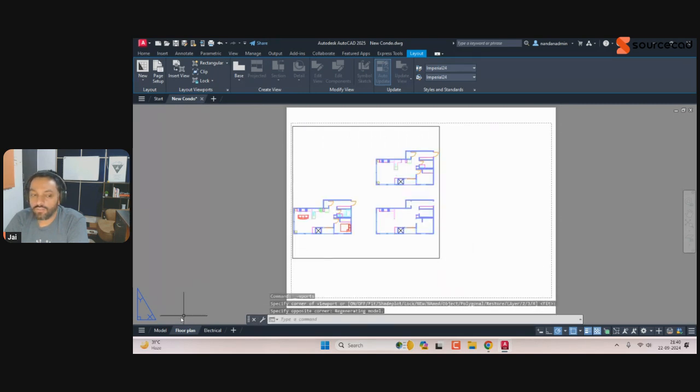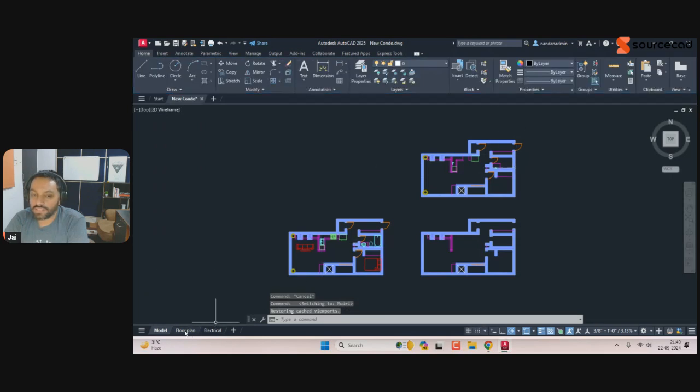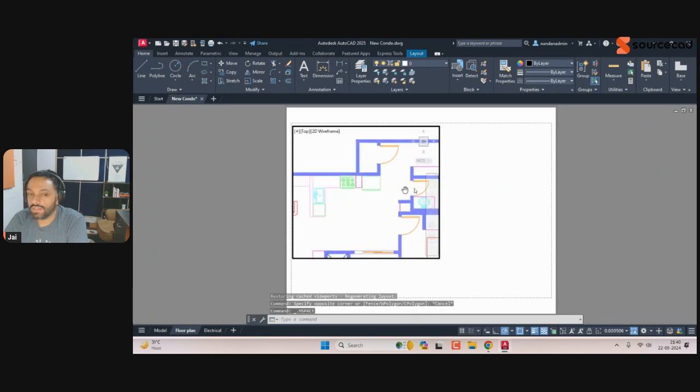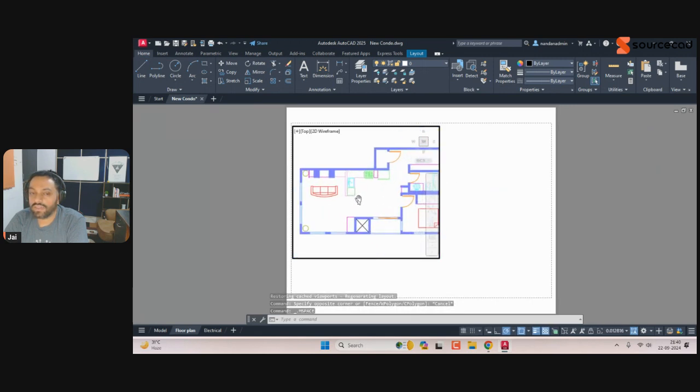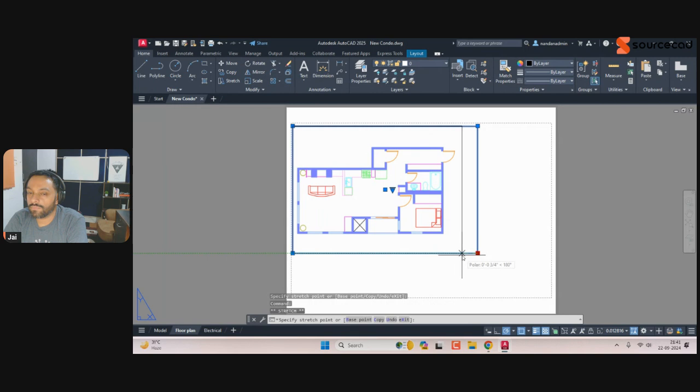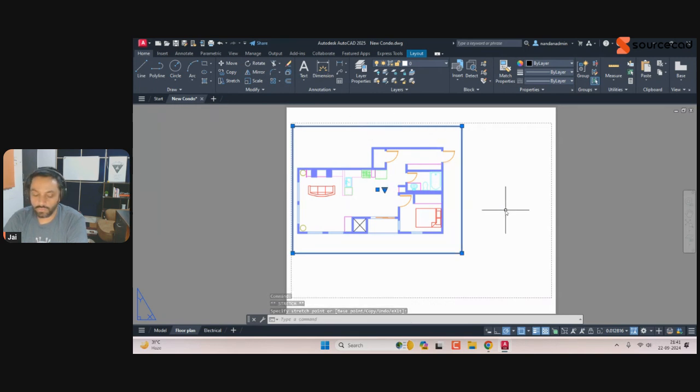And automatically it will show everything from your model space as soon as you make it. But we don't need everything. We just need this one first plan. So double click inside this, zoom in, and just fit your drawing exactly the way you want here. I think this is just sufficient. I'll double click outside, then click the border, and I'll move it like so. You can fit it, and there we are. That's our first view, the model space that we created.